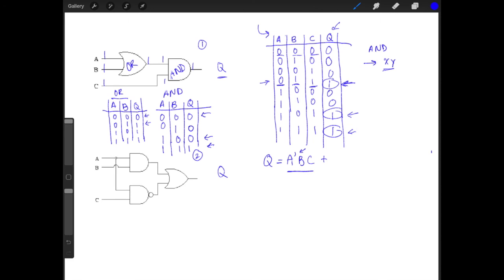So then we're going to do a plus sign, and then write our next situation. Well, remember the plus sign is indicative of an OR gate. So an OR gate has an algebraic expression of x plus y. So that makes sense once again for what we're doing, because we're showing the situations where all the inputs are ANDed, like those specific scenarios, but then there are multiple different scenarios where Q is 1. So in this situation, or in this situation, then Q will be 1.